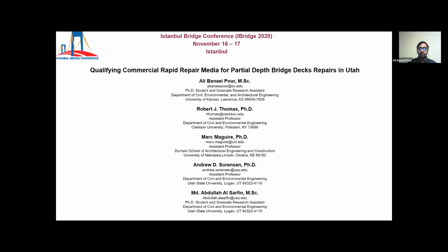I'm actually filling in for Ali Banaipur, who couldn't make it today. Today I'm going to talk about qualifying commercial rapid repair materials for partial bridge deck repairs in Utah. This is a Utah Department of Transportation funded project. For this project, we investigated 8 different rapid repair materials from 5 different manufacturers for their mechanical performance, and then prepared a report.